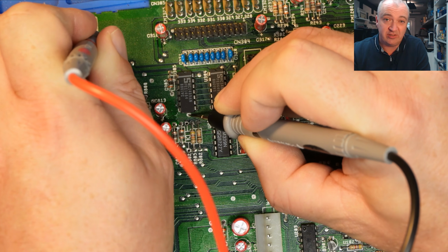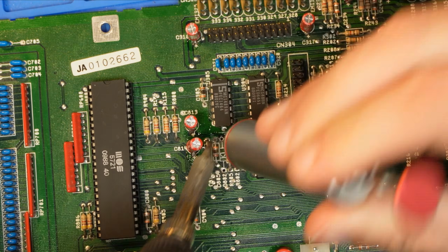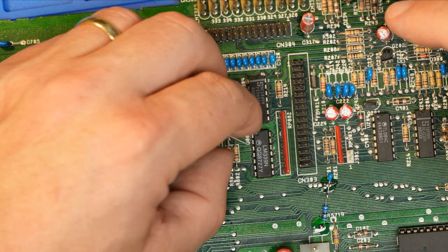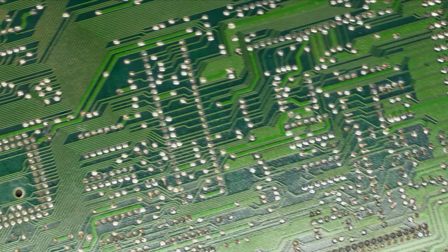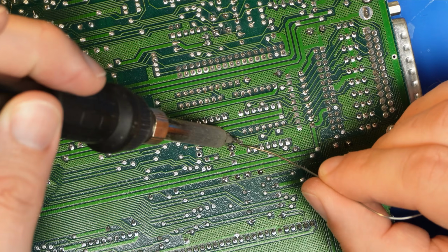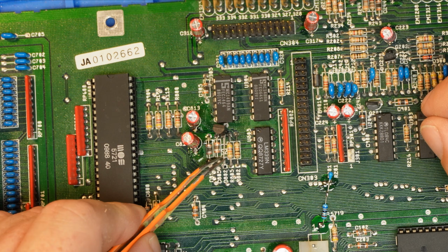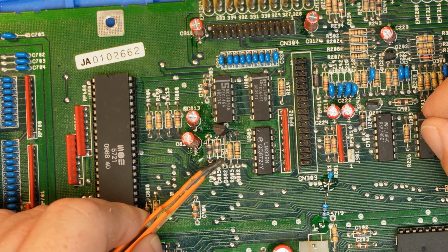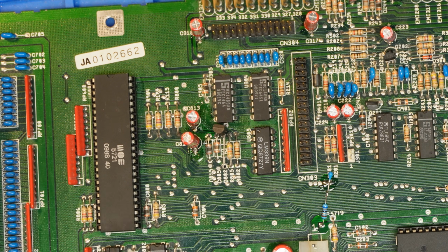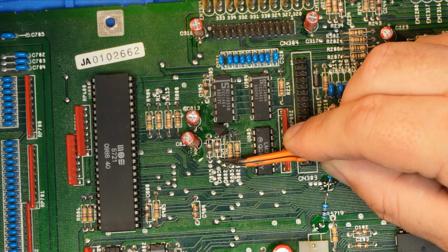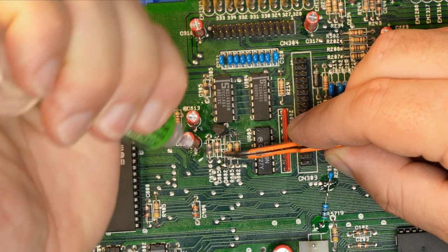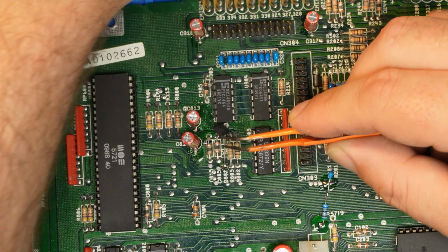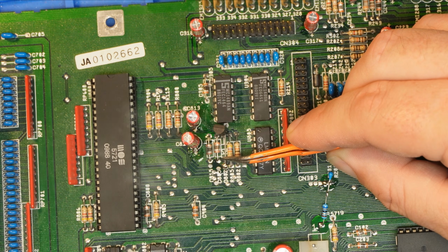So it's just pin 2 to ground. Then that other leg there is just about making that hole where we need to make it off. Just gonna put a wee bit of flux on that and reflow it. It's just not the best joint. There, it's better looking now.